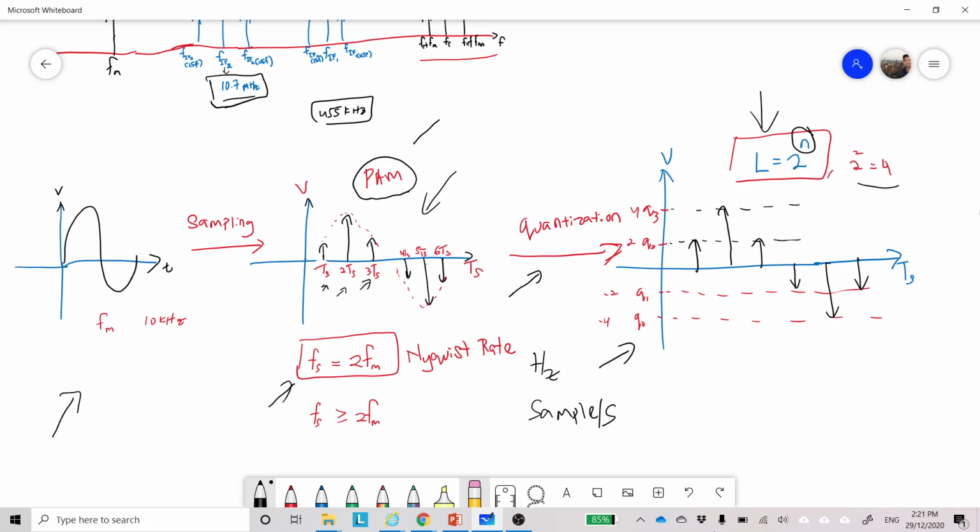Okay, but there's another issue again about the bandwidth. Okay, kalau kita increase the number of bits, we're gonna get many quantized levels, and we're gonna get a better quantization process. However, we will consume a lot of bandwidth. Okay, kita perlukan bandwidth yang sangat besar. Okay, kalau kita menggunakan bit yang banyak, secara tak langsung kita juga akan menaikkan data rate.